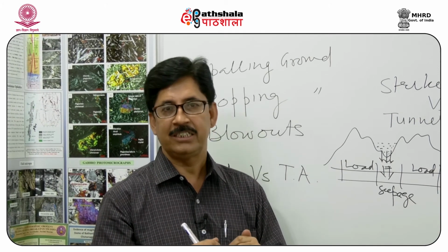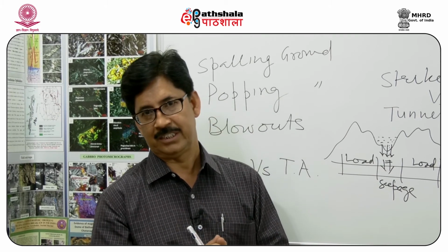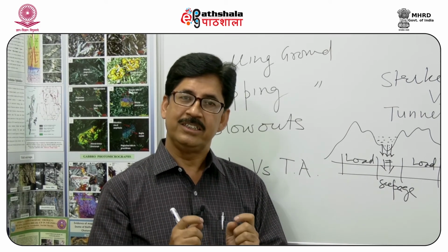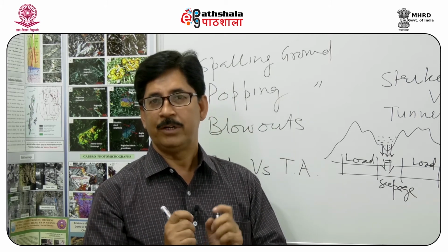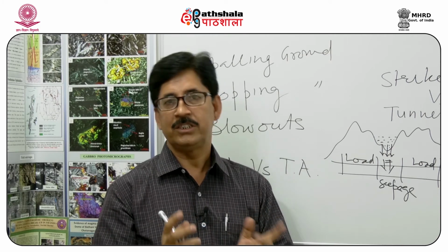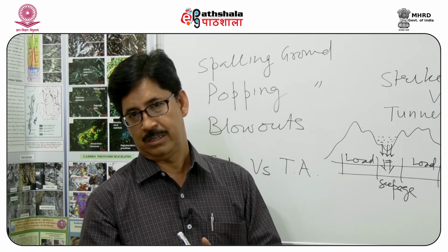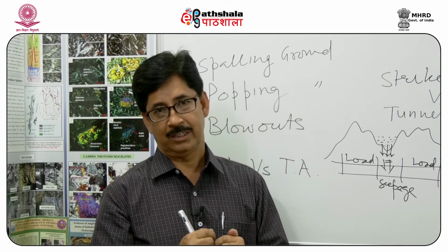As against this, in the synclinal zone, the rocks are under compressive stresses. There, driving the tunnel will be difficult. But because of fewer fractures, the tunnel will be much safer in the synclinal zone. But synclinal zone has a problem of groundwater.